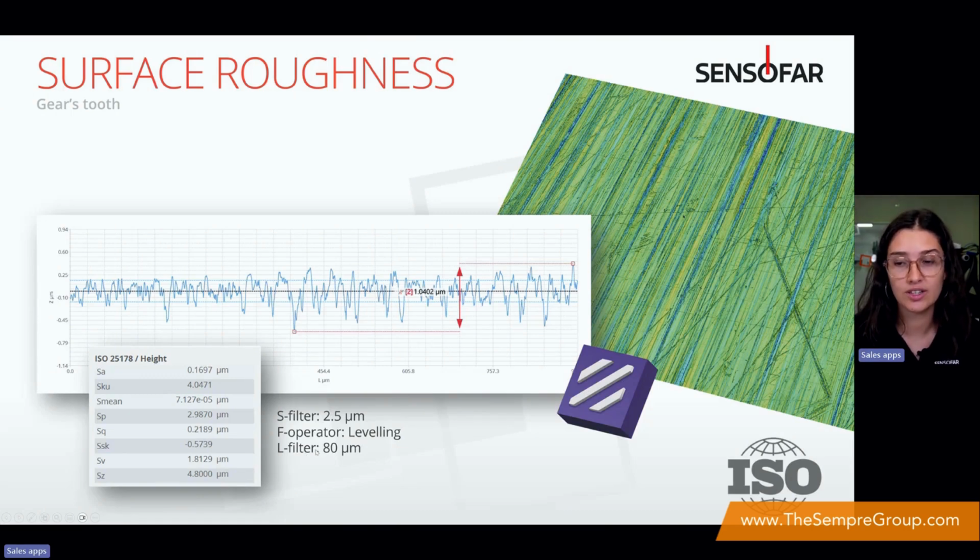I will explain it later during the demonstration, but here you can see what a filtered surface would look like on a gear. Also here you can see a profile and a peak to valley of more or less 1.04 microns. And then here you can see the parameters calculated. In this case, I'm only displaying the height parameters, but if you're interested in the feature parameters or the spatial parameters, we can also calculate them. So for example, here I will look at the top parameter, the Sa, which is the most used. It's 0.16 microns.